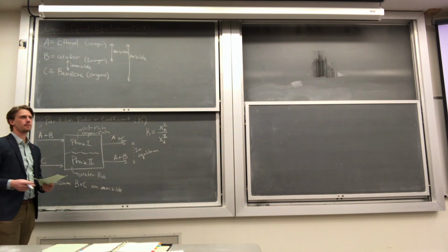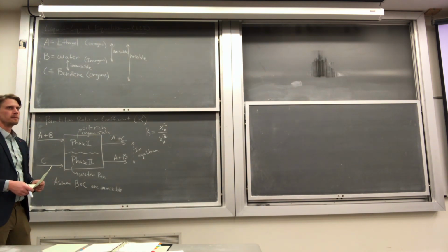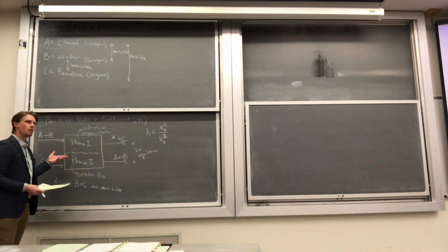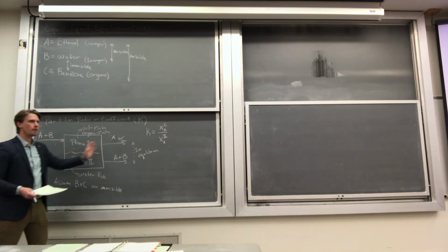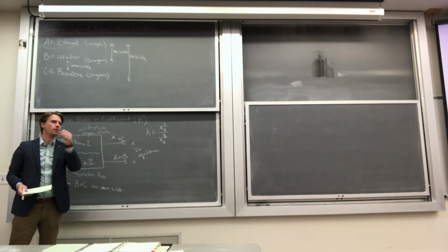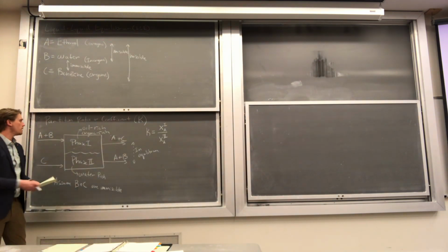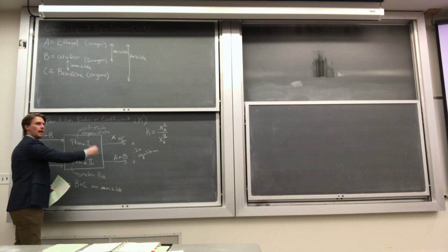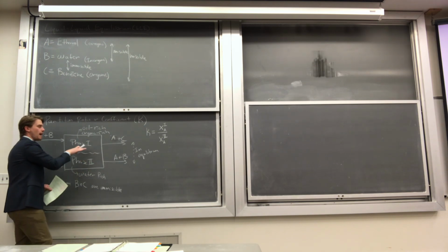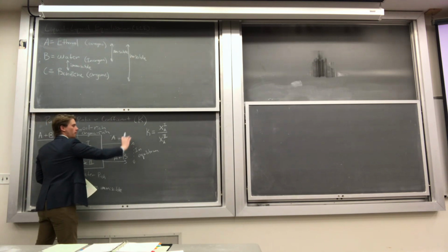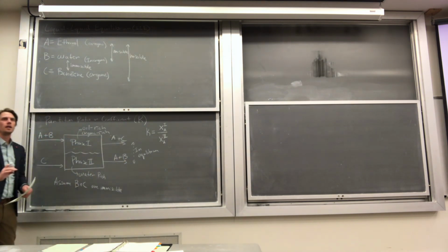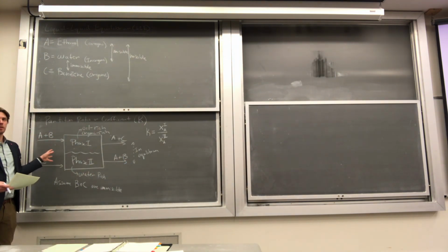Yes? So is this just simply like a separatory funnel where you put the oil, like the organic solvent, mix it, and then do that a few times? That is exactly a liquid-liquid separation. Yep. But in this case, they do it continuously. And so how long the separator is going to be the determining factor for how much contact time that you need. And they'll also put in baffles and things like that so that it's well mixed. And then they have a settling period, and then they have a hole in the bottom and a hole at the top. So another really common example of a liquid-liquid separator is an oil desalter.